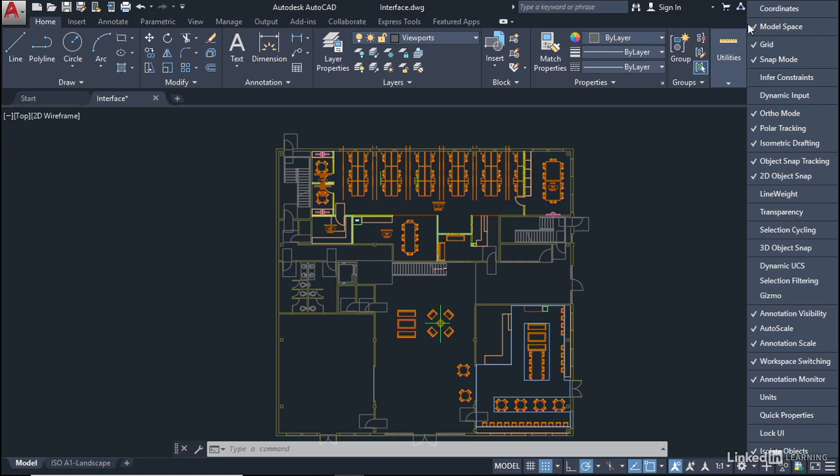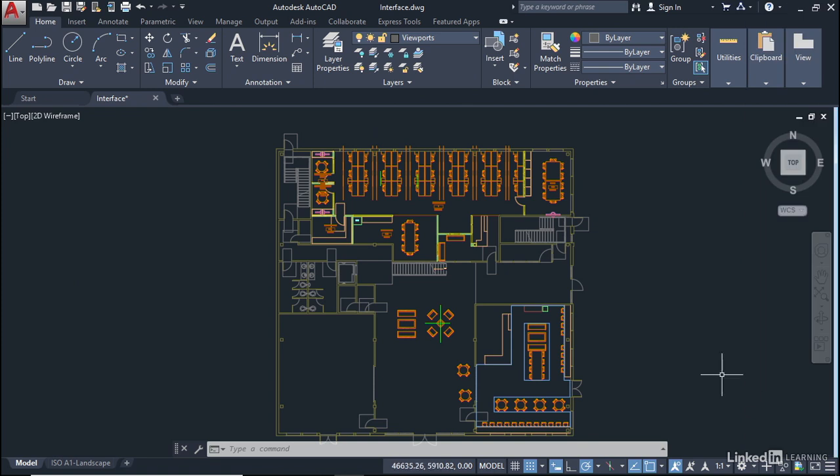Now I'm going to switch on my coordinates like so. You'll see a tick appear next to it when I click on it, and there's dynamic input. I'll also click on dynamic input. There's the little tick that appears next to it. I then go back down here to the little three lines, click on it again to close the menu. So you'll notice now I've got my coordinates here. There's my coordinates there. And coming further along, there's my dynamic input, which by default is always on.